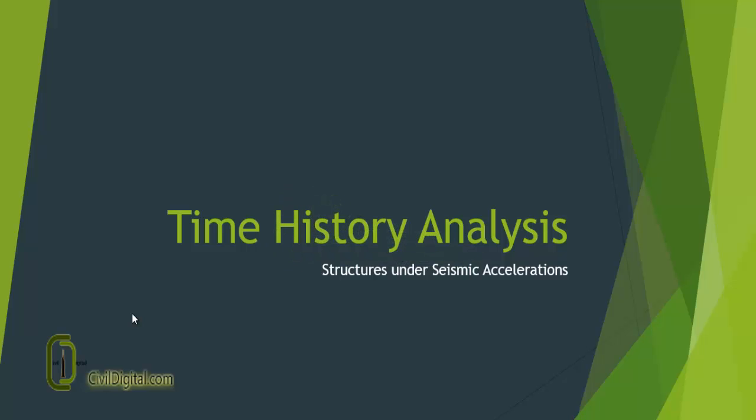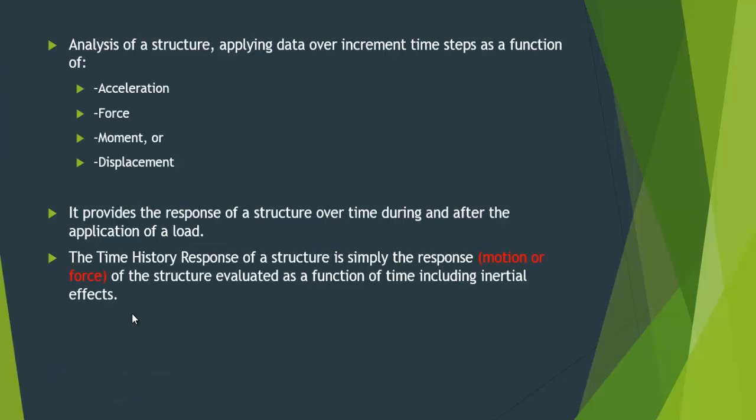In this session, we will learn how to perform time history analysis of structures under seismic accelerations in Staad Pro. In time history analysis, we apply data over increment of time steps as a function of acceleration, force, moment, or displacement. The result that we will get is the response of the structure over time during and after the application of load. The time history response of a structure is simply the response evaluated as a function of time, including the inertial effects.